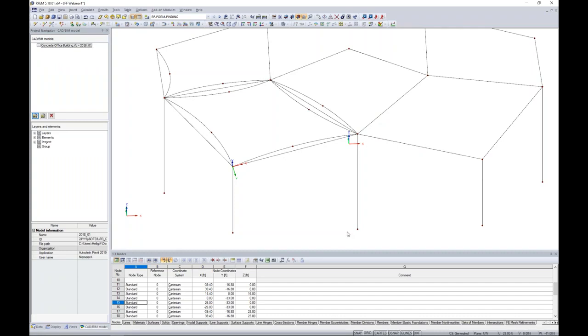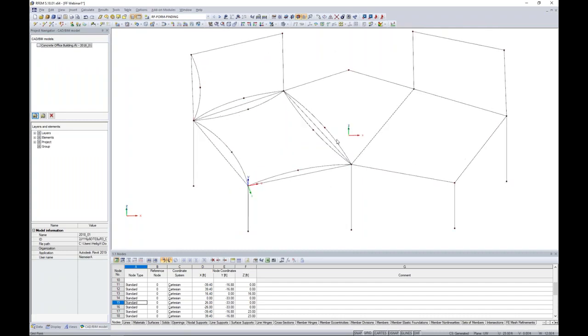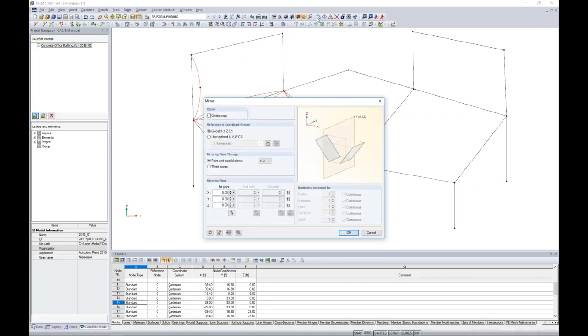So deactivating this grid down here at the bottom, I have these cable elements shown here and I'd like to show them on the other side. So rather than going through that entire process again with our user-defined grid, we can hold down our control key to select what will be these cable element lines and take advantage of our mirroring tool. Mirroring tool, exactly like what it sounds like, similar to what you'd see in AutoCAD.